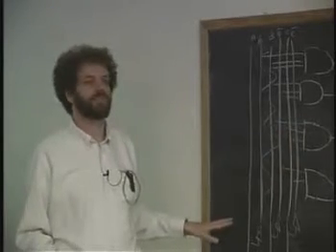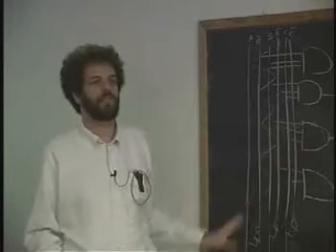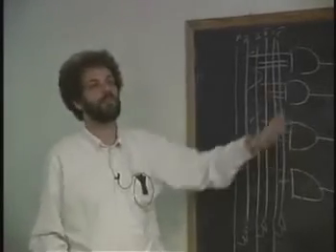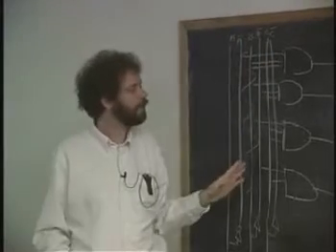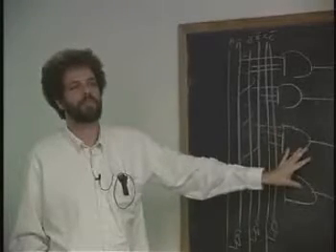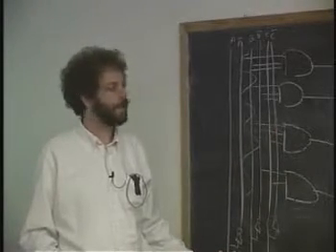Okay, great. 5 inputs: 16. 6 inputs: 32. 7 inputs: 64. The number of AND gates here begins to grow really fast. Okay, and that's awful. It turns out that this is an exponential growth in the complexity of the circuit versus the number of inputs to do parity.